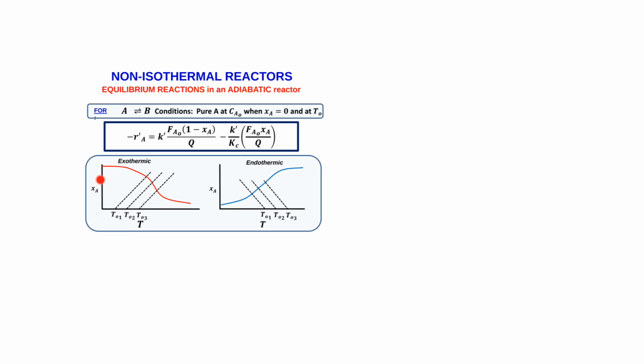So now that we have established our "thou shalt not pass" line for our given inlet conditions, and remember this is not dependent on the reactor type or any energy balances yet, and for the exothermic or the endothermic version of our reaction, we want to superimpose our energy balances first for any adiabatic reactor on these figures. So this linear shape we could derive regardless of whether it was a CSTR or a PFR or PBR reactor.